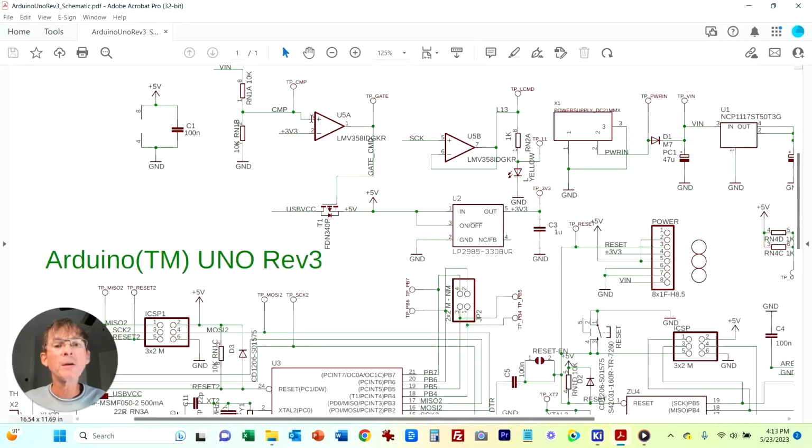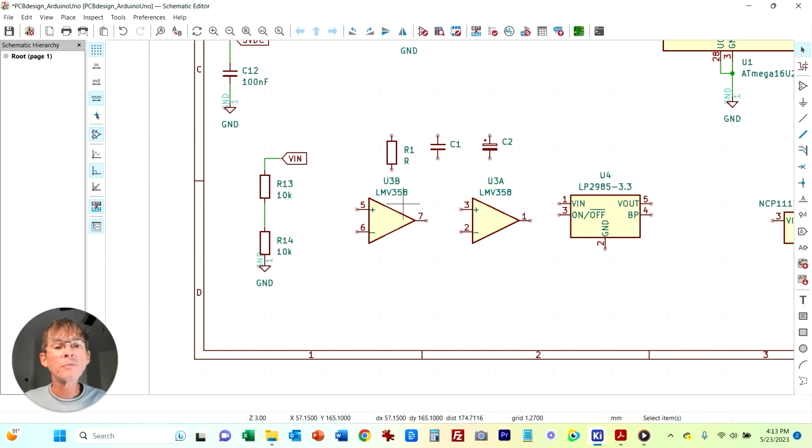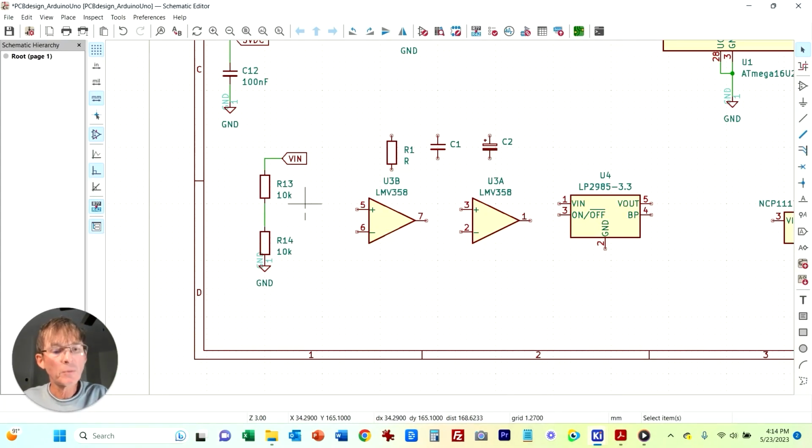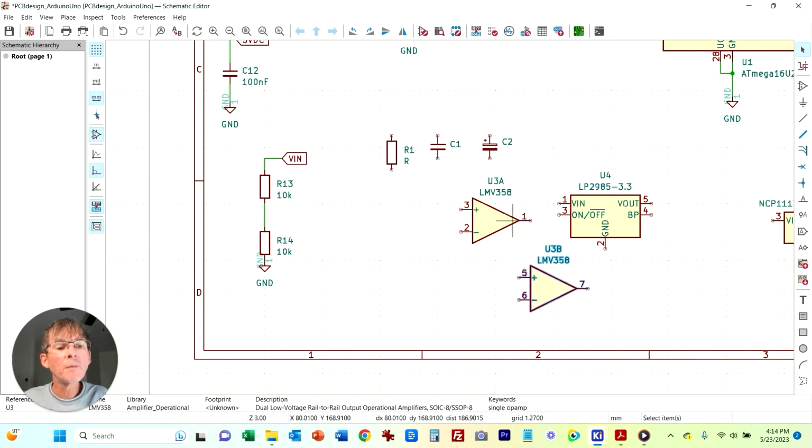And let's go back here. So you've got that divided down, and that divided down goes to the positive terminal of our comparator. So we'll just type this here, just to keep it the same. You can see they've got a U3, B, and A. So it's all in the same chip, but the pins are different because this chip has 2 of these. So I just want to make sure I'm using the exact same one that they're using in the schematic. So they are actually using A. Okay. So I'm going to get rid of that. Move down to there.